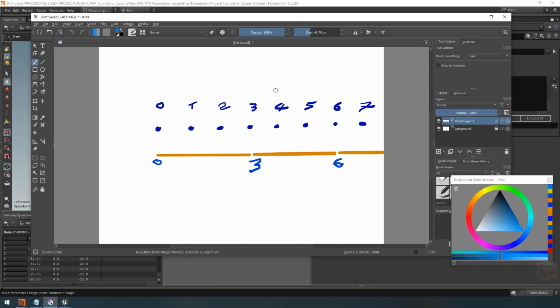Now, if you want to make this work with VEX, with an equation, with math, then the best way to do that is to simply collapse everything in this range down to a range from 0 to 1. So basically, this would become 0, this would become 1, this would be 2, and then 9 would be 3, right? And then you can simply round to an integer, meaning that if we snap these points, 0 would be 0, 1 would be 0, 2 would be 1, 3 would be 1, 4 would be 1, etc.